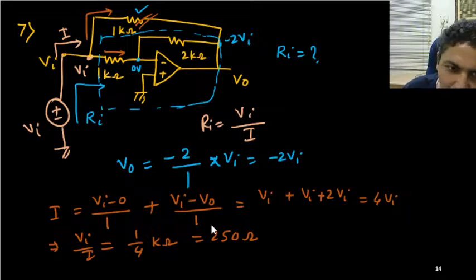So practically what is happening? If you want to use integrator, then you need to use one practical integrator. One resistance should be connected to your capacitor in parallel, right? Then it will become practical. So it will also be stable for DC input. So that's how this practical circuit works.